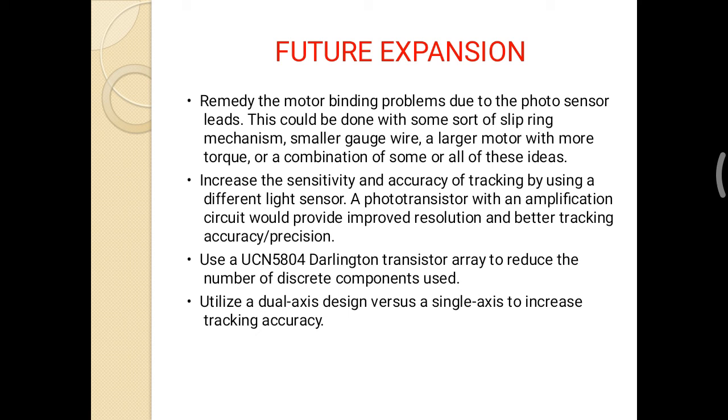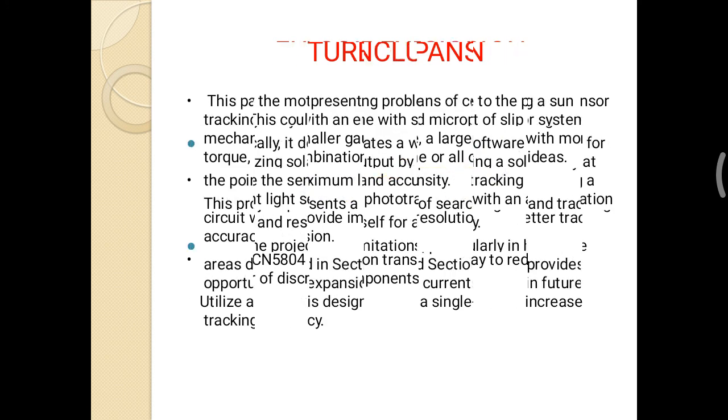And use a UCN5804 Darlington transistor array to reduce the number of discrete components used. Utilize a dual axis design versus a single axis to increase the tracking accuracy.